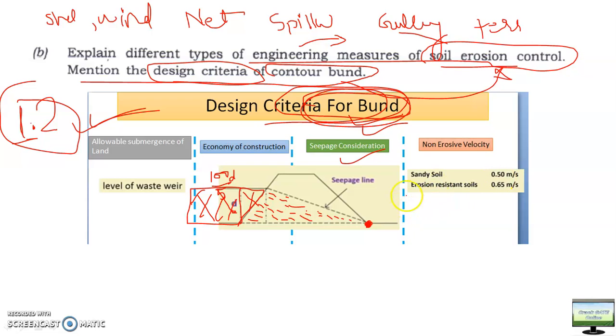So suppose you know the slope of the seepage line. Slope will be given in terms of depth, because this is D, then this height will also be D. Suppose seepage line slope is 5:1, then it will become 5D, and you know the side slope of this side of the trapezoid, suppose it is 1.5:1, then it will become 1.5D. Okay, this length.